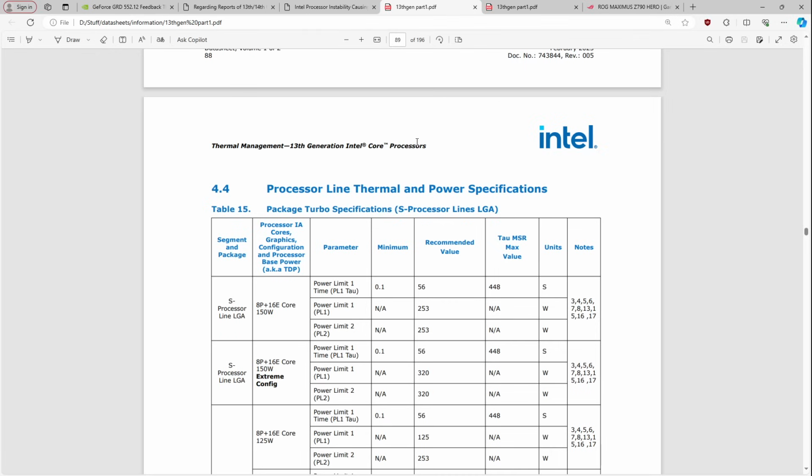Then they try to run Cinebench, and it just instantly errors out. They press run, and it just spits out an error message. Then they show how if you underclock the CPU, it works. Yeah, because that CPU came from the factory with a VID table that doesn't have enough voltage to run Cinebench without power limits.